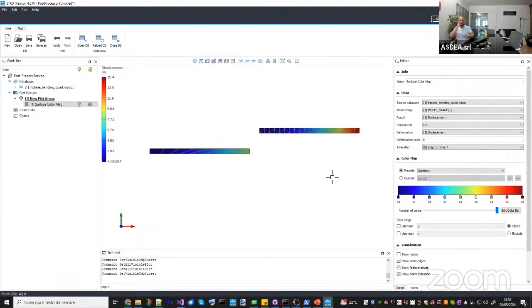Because I often see people that try to use as much as possible quadrilateral elements because they have learned that quadrilaterals are better. And in order to use them, when you have a very complex geometry, you end up having very distorted elements. So in that case, it's better if you use a Delaunay mesh and you produce a good quality triangular mesh and a triangular element, because in that case, a regular triangular element is better than a distorted quadrilateral, okay?